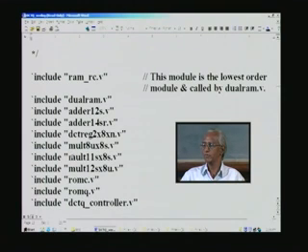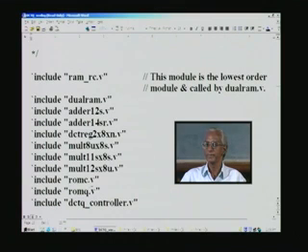We have also seen the design of the multiplier for 8U into 8S. U stands for unsigned, S for signed, and as usual we also gave assignment for 2 other multipliers, and that is precisely what we are going to use here. We also covered the design of ROM-C as well as CT. So these are the C and CT matrices for the evaluation of DCT, which requires the multiplication of 3 matrices C, X and CT,